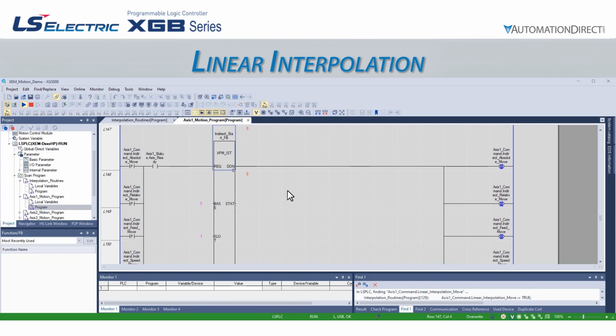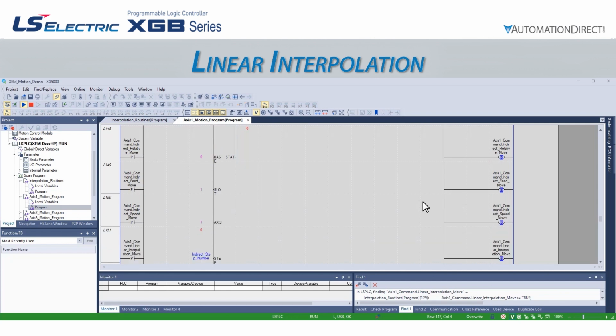We set the indirect step number to 10 earlier, so this is the line in the position data table for axis 1 that will be executed for a linear interpolation. Finally, we see that the bit will be reset once the indirect start done output goes high. This occurs as soon as the move is started, so it should not be used as an indicator of motion completion. To further dive into the details of step number 10, let's look at the position data table for axis 1 in XGPM.